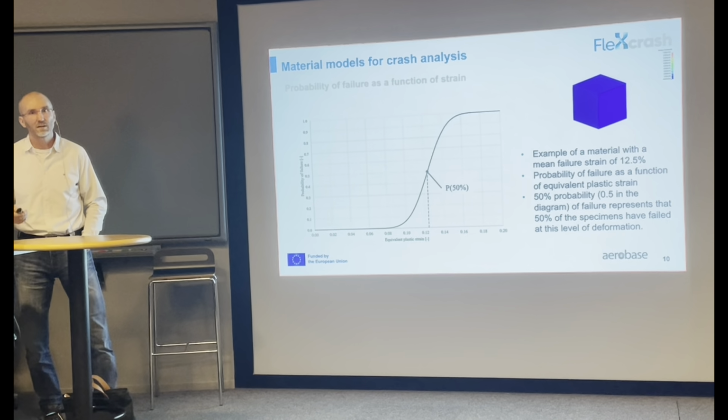Another thing with failure strain is that it is dependent on your stress state. So we usually define it with something called the stress triaxiality, and that is the stress condition. So typically in a uniaxial tensile test like this, where you have a hole in the center, then you have a value of 0.33, and then if you have more shear-like behavior, then you close up to almost 0. And in plane strain condition, you have approximately 0.58. So you need to create these failure curves. This represents the failure strain at that current stress triaxiality.